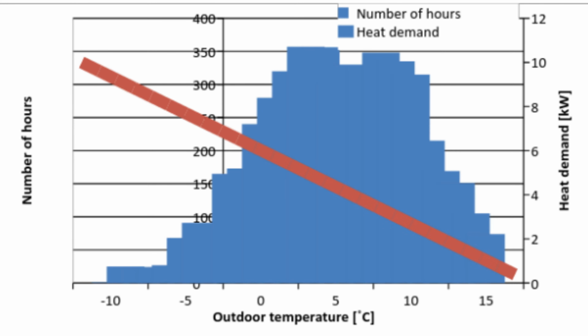So when we are dealing with calculations, we are not dealing with COP, we are dealing with SCOP. It means seasonal coefficient of performance. And this is for the whole heating season where we have average efficiency. So the average heating season is not at the lowest outdoor temperature. It's on average. So usually it's above zero.